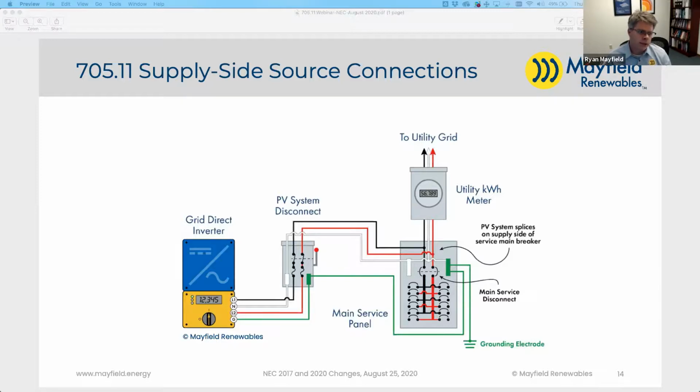So I think that's what we were looking at, trying to figure out what's the best answer. It seems like it's a really low risk, not a zero risk, but a very low risk situation. And by putting them as close to that point as possible, I think you're definitely trying to protect those conductors as best you possibly can, short of an inline fuse or a fuse holder built into a combiner box or an inverter.